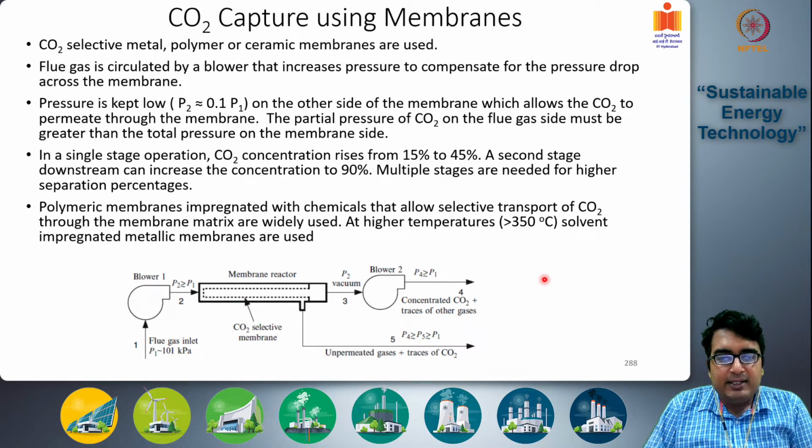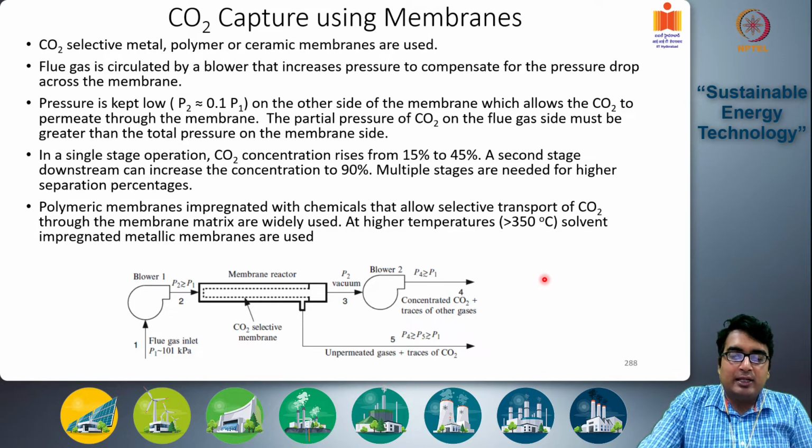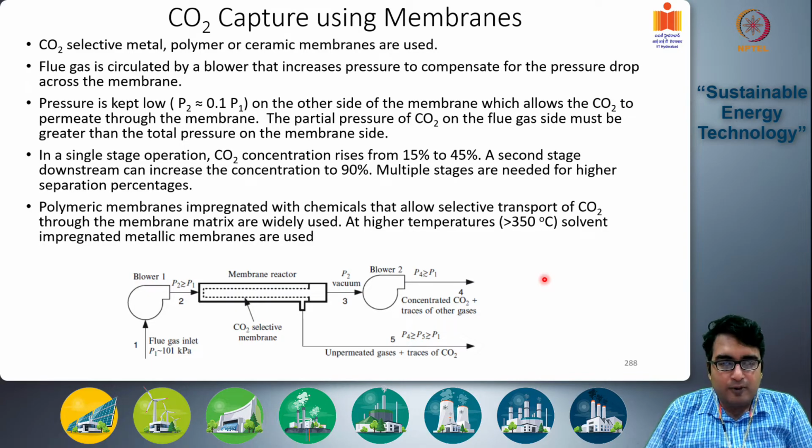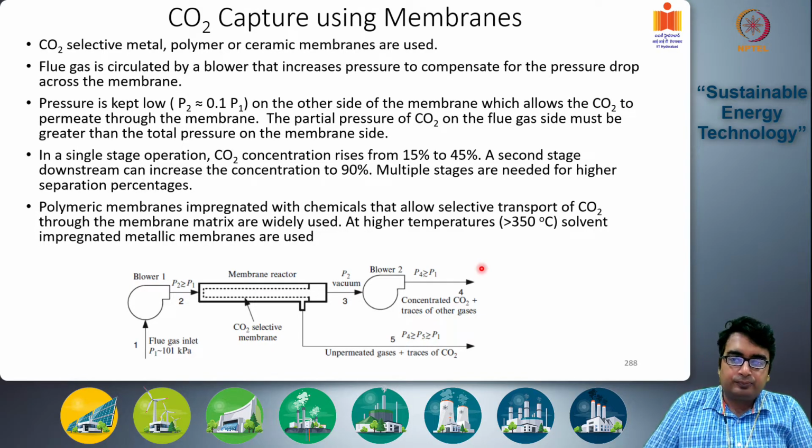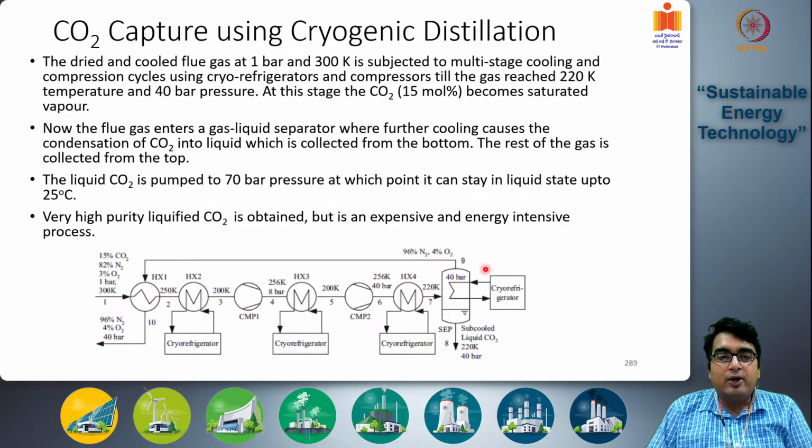Till now we were discussing different technologies of CO2 capture, including sorbent based absorption of CO2 and separation of CO2 using a set of semi-permeable membranes. The last technology that we will look at is the capture of CO2 using cryogenic distillation. The basic idea here is we are going to pressurize, cool and hence liquefy CO2 and separate it through condensation, primarily distillation in this case, from the other components of flue gas like nitrogen, oxygen, etc.